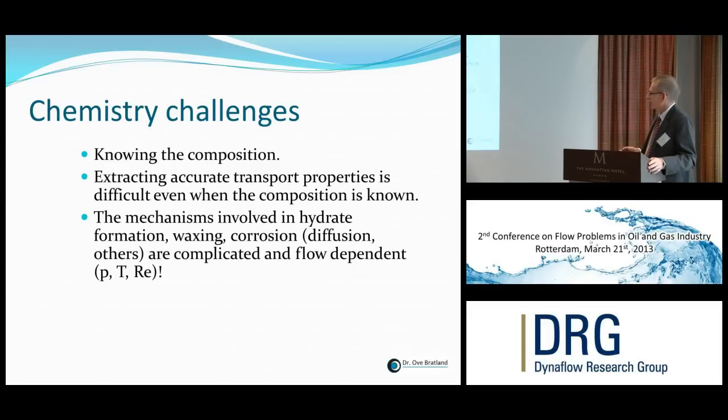The mechanisms involved in hydrate formation, waxing, corrosion, diffusion, and others are rather complicated. And we can't just go to the chemists and ask them and they will give us the whole answer, because it just so happens that how this forms in the flow line also depends on pressure, temperature, and Reynolds number. So the chemist can't solve it alone, and we, on the fluid mechanical side of things, can't do it either. We have to cooperate, obviously.